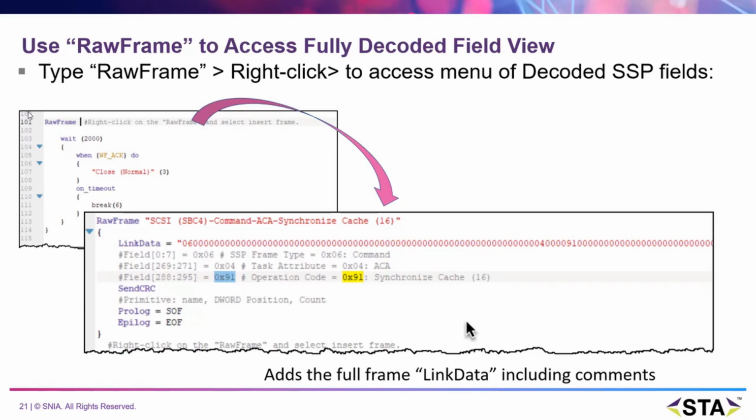This enables stress testing of devices under controlled conditions, helping to uncover edge case behaviors, validate error recovery mechanisms, and assess protocol robustness. The ability to precisely control replay sequences, including OOB handshakes, SNW parameters, and TTIU frames, is essential for thorough conformance testing and debugging interoperability across different SAS implementations.